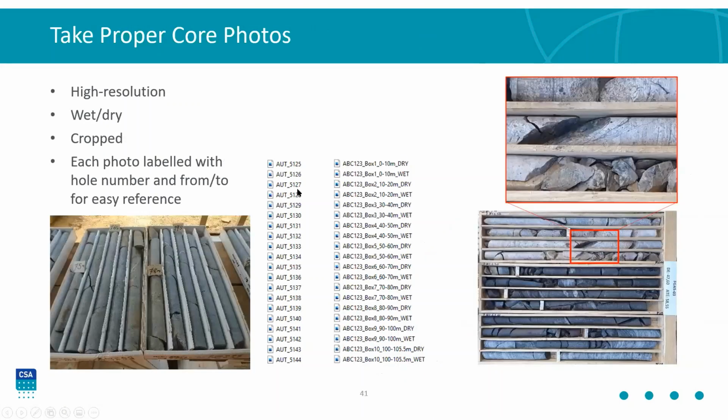This relates back a bit to the RQD data, and something that I think a lot of companies are taking core photos, but just make sure you do a thorough job of it. I cannot overemphasize the usefulness of good core photos to structural analysis after the fact. I'm a structural consultant, and there is an enormous amount of work that I can do using core photos, which saves people having to fly me to the other side of the world and haul out drill core and log structures. You can do a heck of a lot.